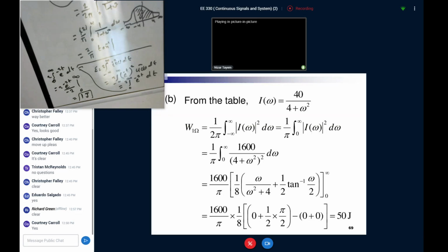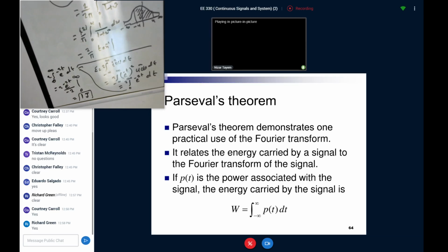Because if you get back to the definition of the work done, the slide talks about a 1 ohm resistor, and instead they did the 2 ohm resistor. That's a mistake in the slide. It's not a big deal. Yes, I understand. So the work done is equal to the integral from 0 to infinity of P of t dt, where P of t here is I of t squared times R. R is the 2 ohm resistor, so we're getting 1 joule in this case, okay?